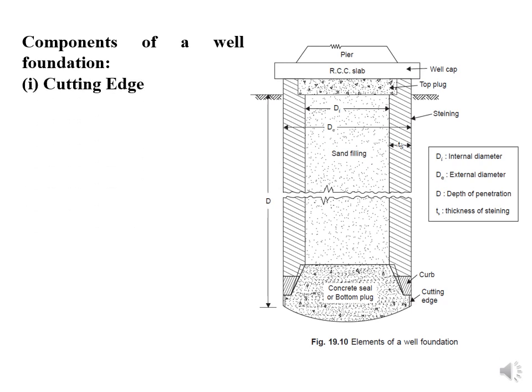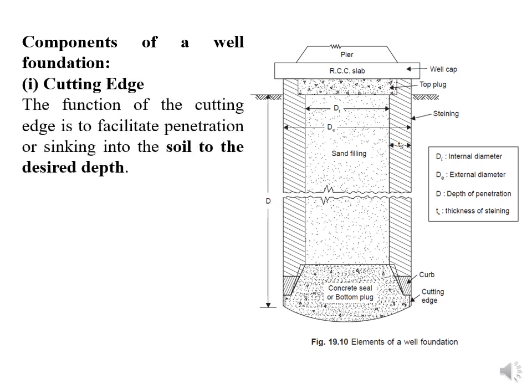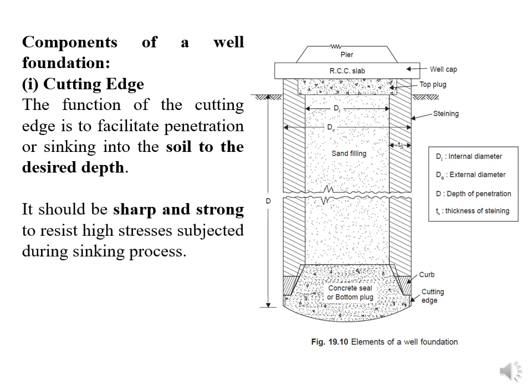We can see here the cutting edge. What do you mean by cutting edge? At the bottom, you can see the cutting edge is given. The function of the cutting edge is to facilitate penetration or sinking into the soil to the desired depth. It should be sharp and strong to resist high stresses subjected during the sinking process. It should be sharp, otherwise it will not go inside the earth.